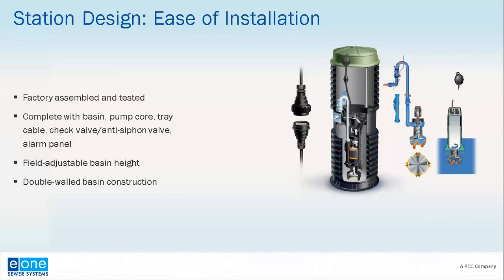Again, with the total focus on maintaining low operation and maintenance costs, we want our systems to be easily installed. They're factory tested. We want them to be plug and play on site so that there's as little human assembly required as possible. So everything is factory assembled and tested at our factory before it leaves. It comes complete with a basin, and a pump core is inside that tank. It's got the check valve, which is intrinsic and included as part of the design, and the anti-siphon valve. The alarm panel would be tested before it leaves our factory. There's no assembly required of these individual components.